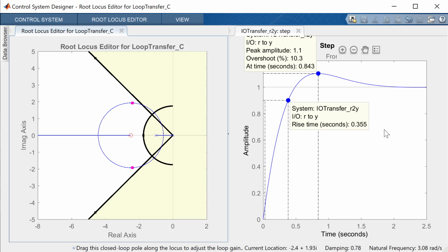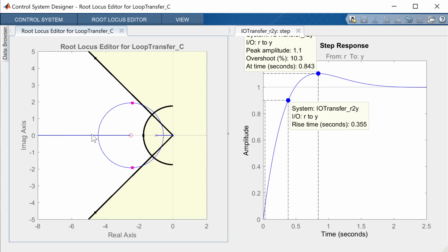So anyway, this is a brief intro into how to use the RL tool so that you can approach some of these design problems. Again, these give you exact information. This gives you directionally correct information based on a pure second order system. And your knowledge about how adding poles and zeros and other things into the root locus, using the controller to add those terms, is going to help you figure out how to change the shape of the root locus so that you can achieve these design specifications.